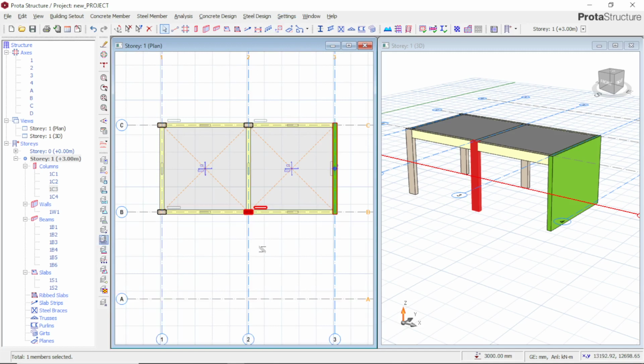So with that now, it's certain that this is what I want to do. I want to show you more. This one, I go to the column on the layer. If I off it now, can you see the column is disappearing? The ones that were here have disappeared. But I want it back again. I come to wall. I want to hide the shear wall. I come to shear wall, and it is hidden. See, this wall is hidden. I can come back to the shear wall, I on it back, and it shows back. I can see how wonderful it looks. So you can off anything here.